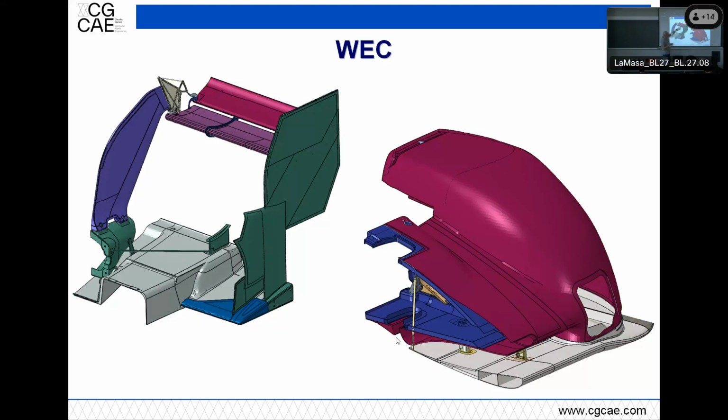But the rear is easy because you have a flap and you move a flap rigidly. The front, there is no flap. So they wanted to have a sort of flexure again in the trailing edge to allow this to move. And this was the interesting part. Because, of course, you cannot place a hinge in there.